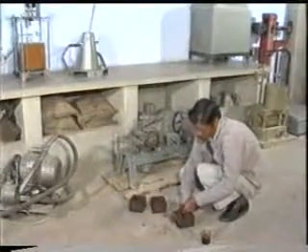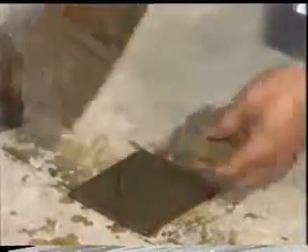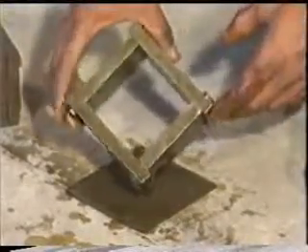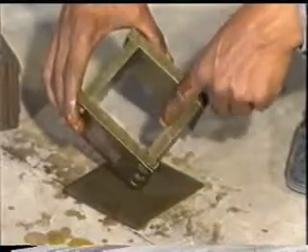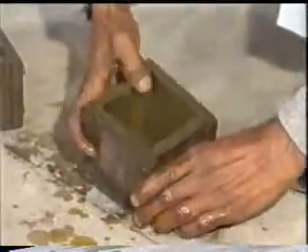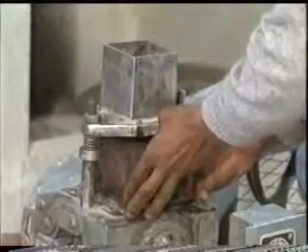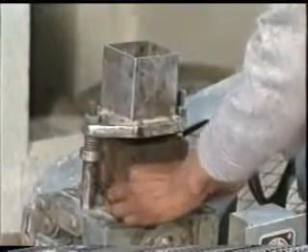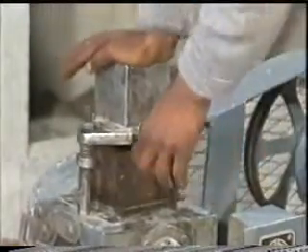Before adding the measured quantity of water to the dry cement sand mix, apply oil to all the interior faces of the mold, each side of which measures 7.06 centimeter. After oiling all the inner faces of the mold, including the base plate, place the assembled mold on the table of the standard vibrating machine. Firmly hold the mold in position by means of suitable clamps provided.